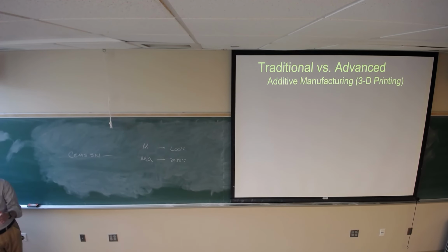If you change your composition, go back to the company, and 6 months later they'll give you a slurry that will work for photolithography. No, not interested in that. And then if you do the robocasting, you have some problems of how you control flow. We have good ideas about that. But the bottom line is that if you get a powder that will flow in 3D printing, it will not sinter, period. You can engineer a powder to flow that jacks up the surface area for potentially able to sinter. Still doesn't sinter well. It's pretty cool.